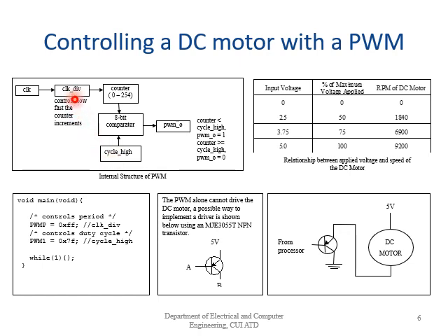Okay, so we need to put that 7F here in cycle high, and we need to put FF here. Why do we need to put FF here? Because we have checked that in the case of FF, we have the best working of the circuit. So we can apply different values for clock div, and on the basis of DC motor speed and its continuity, we can set the value of clock div.